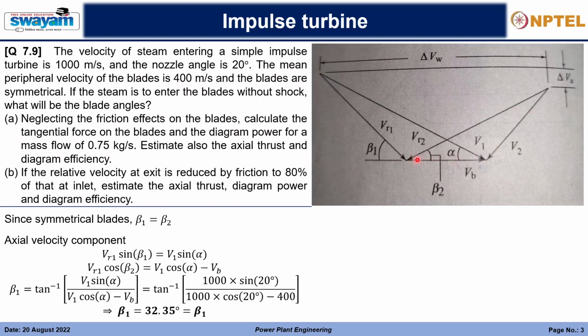That is why we will have to go from this point to this point, and if we draw a vector like this, we will get this actual exit velocity. So this is also a very important term, because this is v2. The v2 is the exit velocity. This is very important when we will be doing staging. From one stage it is going to another stage, so we will have to consider the angle. The initial angle may be alpha, but the final angle may be different than alpha. So we will have to evaluate the value of v2 and accordingly evaluate the values of this delta. So we will be talking about that next.